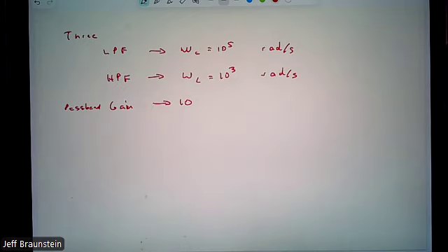From the left, you start with high pass, right? It doesn't matter. You can do either order. It's multiplication. Is there a difference in 2 times 3 versus 3 times 2? So multiplication, any order. So we're doing low pass filter times gain times high pass filter, or high pass filter times gain times low pass filter, whatever we want. Low pass filter times voltage follower times high pass filter times voltage follower times gain. I mean, that's needlessly complex, but.